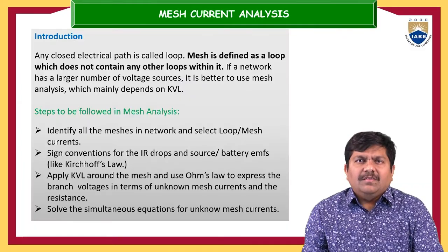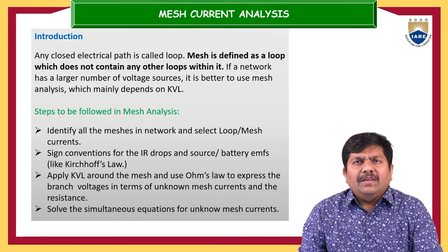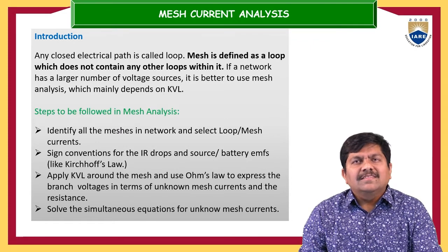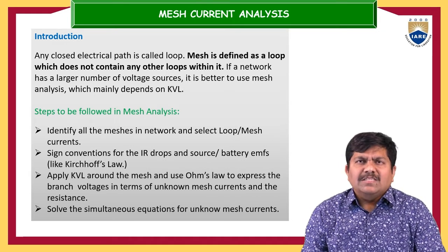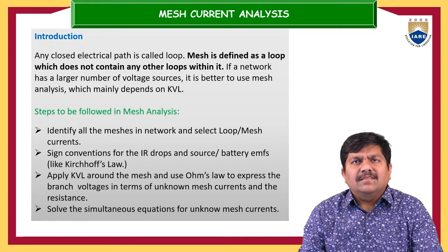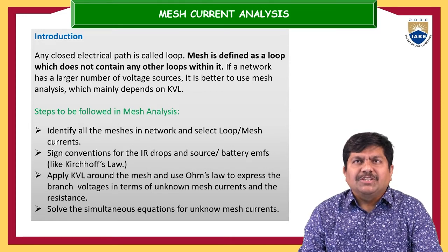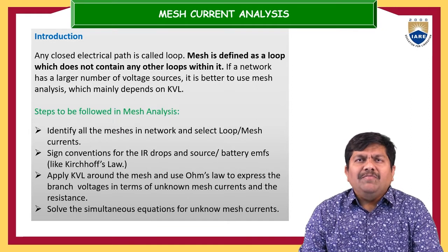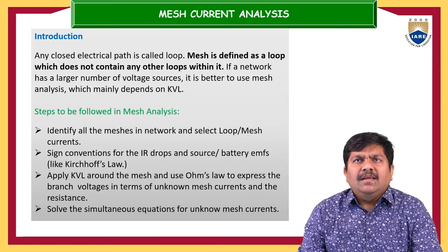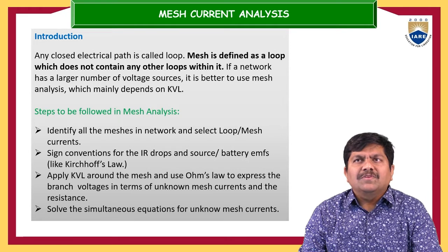First, knowingly or unknowingly, very many times we utter mesh analysis, whose other name is loop analysis. What are mesh analysis and loop analysis that we are going to discuss in today's session? Coming to the introduction, how can we define mesh analysis? Any closed electrical path is called a loop. A mesh is defined as a loop which does not contain any other loops within it.